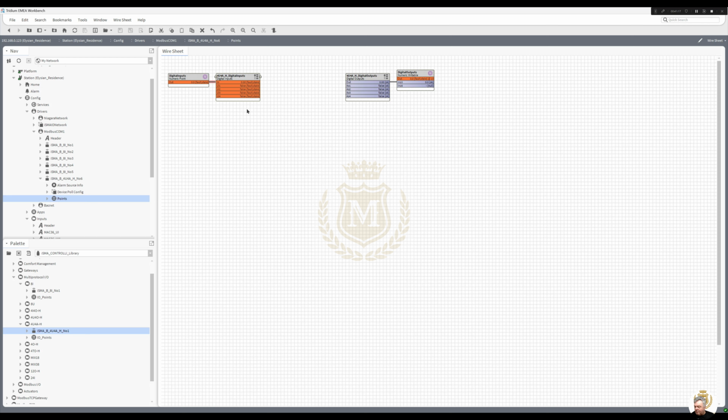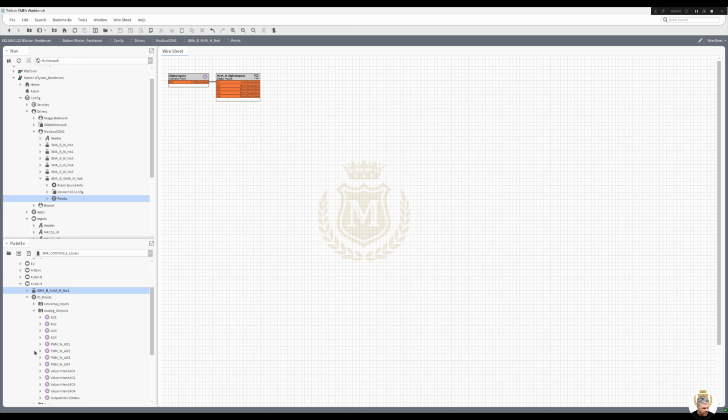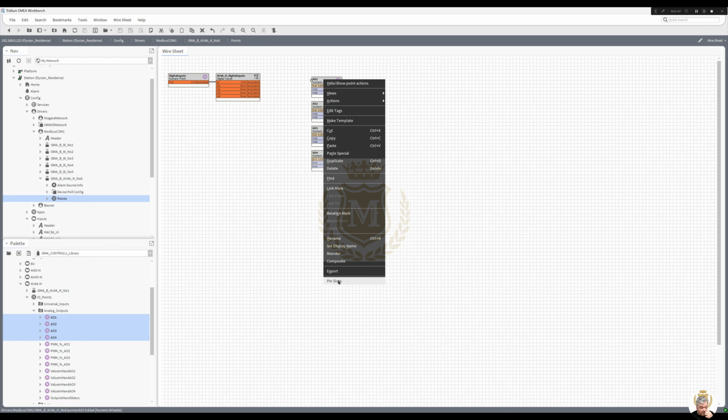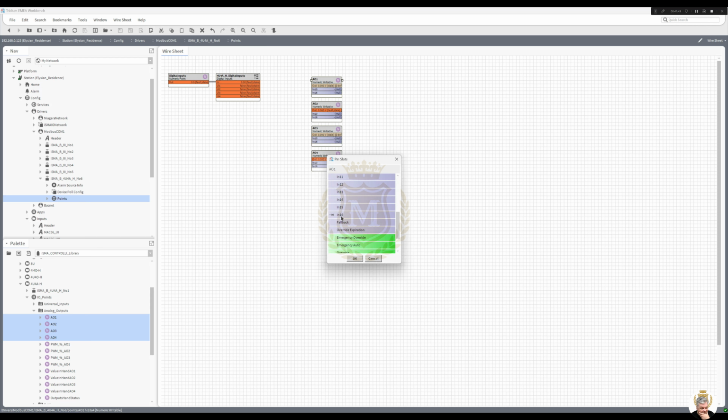And then of course we've got boiler 1, boiler 2, boiler 3, and then we've got the AHUs, which we don't want that because we're not using them as digital outputs. So what we're going to do there is we delete them and we go to our points, analog outputs, and put them across to there. Just tidy it up a little bit and take out in 16.